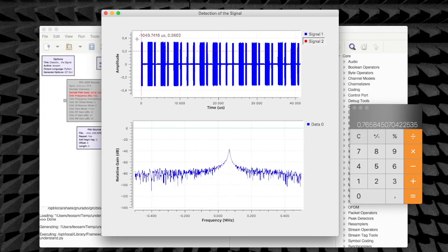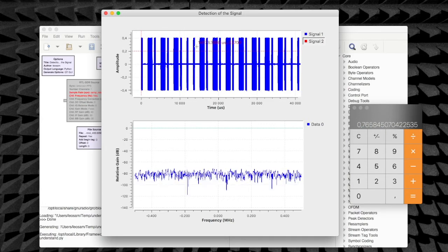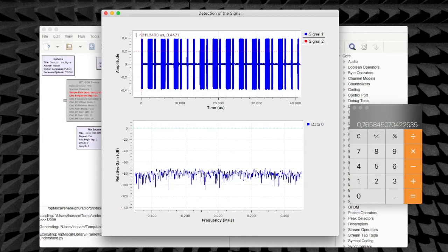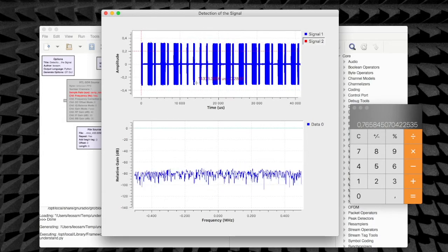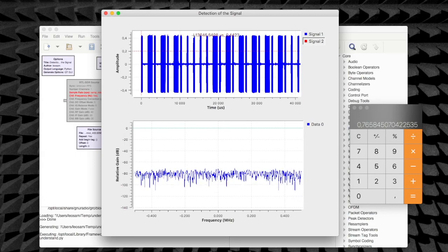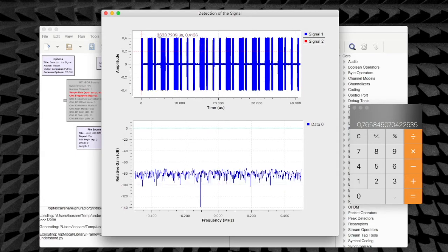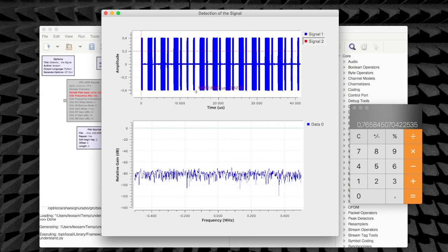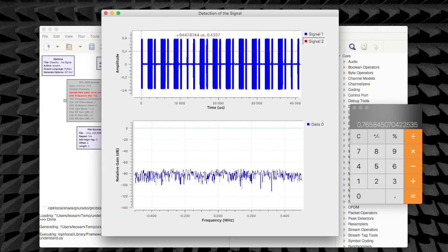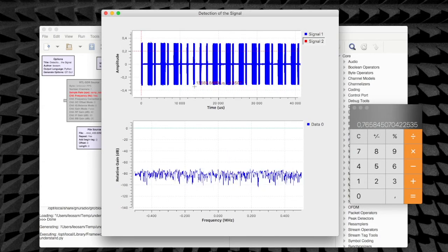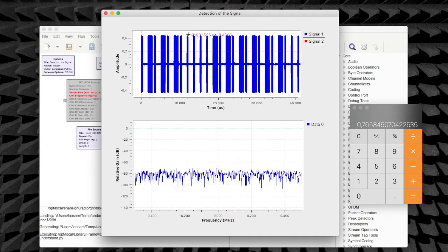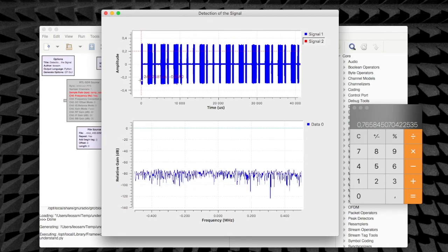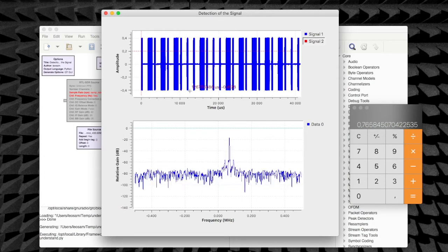We already have noticed that this part of the signal up until this point is always constant, meaning that this is either a preamble or it corresponds to the channel that has been selected at the remote control from channel 1 to 4. We'll look at that later by trying other channels to see if this changes. But right now, this is fixed for every button press. So we can decide that this is constant for this remote control at these frequencies.